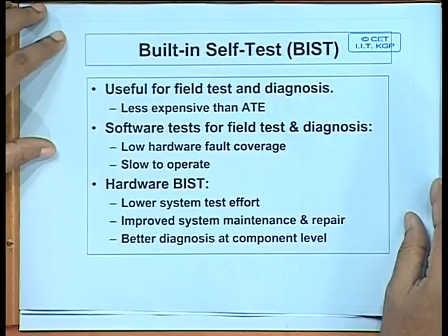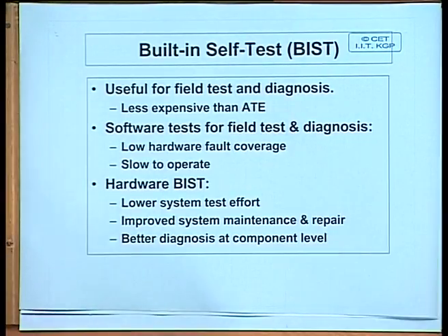There is another general philosophy which is also in widespread use, that is called built-in self-test. Here we are trying to add some more circuitry inside the chip so that the chip can test itself, but there are a number of issues that need to be addressed here. So, in the lecture today we will try to address some of these issues which are posed by the BIST, built-in self-test techniques that are used. First let us try to see what this built-in self-test technique is and what it involves.